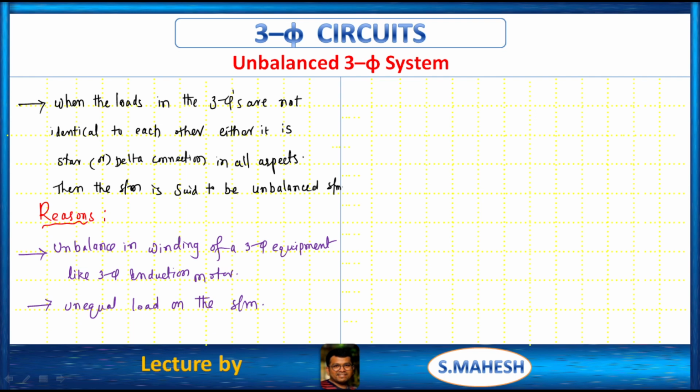We all know that in a balanced three-phase system, the summation of all phase currents should be equal to 0, and all line currents should be equal to 0. In that case, we don't have any neutral current because all are balanced, right? But in this case, all three phases are unbalanced. Obviously, we are going to get the neutral current. If we add the individual currents, for example the phase currents, by adding those three phase currents we will get some neutral current due to unbalanced load, right?